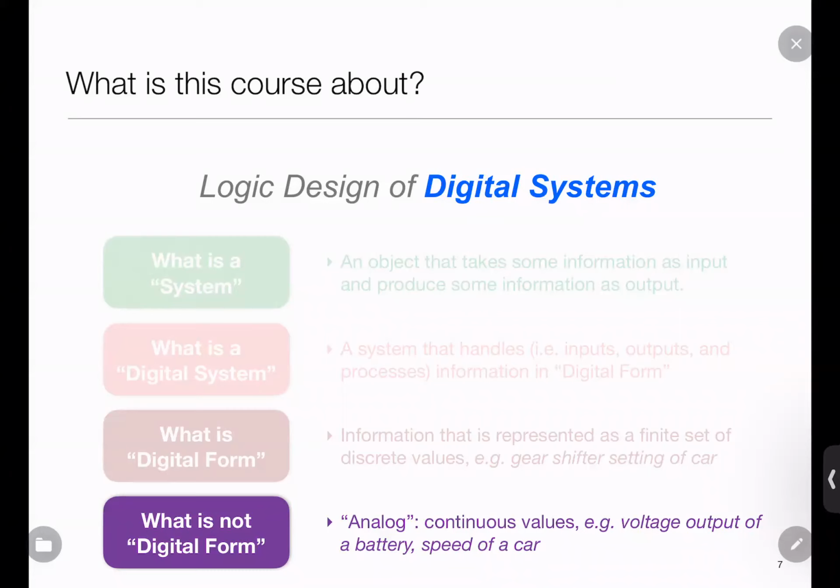So many of you I know are fairly advanced in EE, so I'm sure you have heard of things like sampling. I take a signal and I sample it at certain points in time. Maybe I sample it periodically. Does anyone know how we decide how often to sample a waveform and still be able to recreate it? Yeah, okay, fine. 2 times the highest frequency. Excellent. So it's called the Nyquist rate.